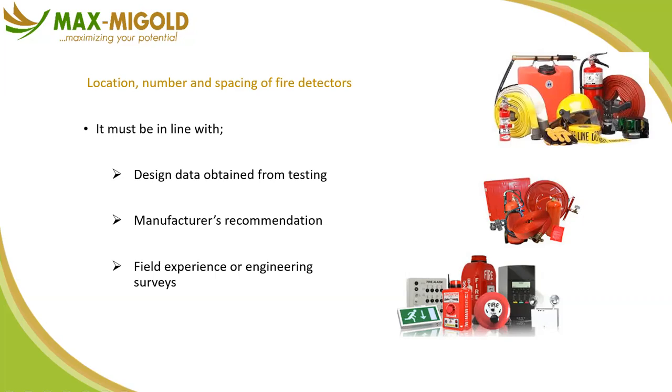If the material stored in that area is either light material or heavy material, meaning either a less hazardous material or a more hazardous material, then the number of smoke detectors will also change. So I will leave this to allow for design specific situations.